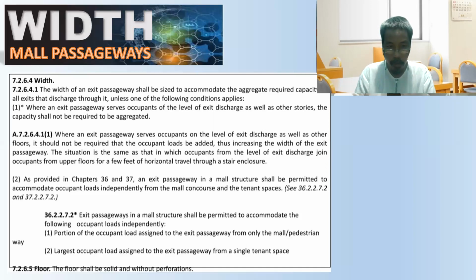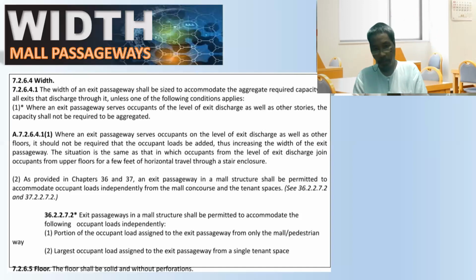Number one, the portion of the occupant load assigned to the exit passageway from only the mall pedestrian way. Number two, the largest occupant load assigned to the exit passageway from a single tenant space. It shall be permitted.